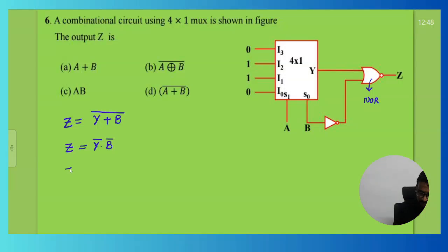Right. So from this, Z is equal to what we can say now, Y. Y is given as what, you tell me now. This is 1 and 2 minterms. So obviously this we can say directly is an XOR gate now. So even if we expand this, what will come here? This is nothing but 1 and 2 minterms, XOR gate only. So this Y value will come to be A XOR B. Then what about this Y bar, you tell me? Y bar means A XOR B whole bar.